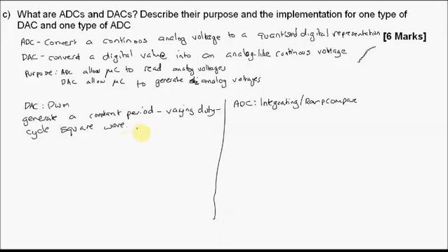And our analog voltage is proportional to the duty cycle. And we put a low pass filter on to make it look more analog like.